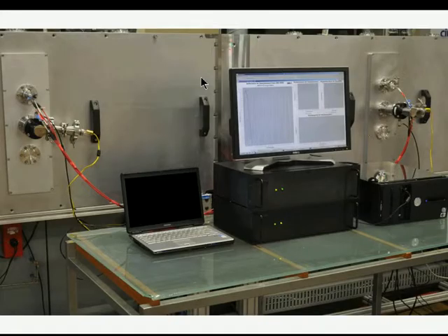On this picture, we are showing how our prototype system was installed in a real manufacturing line. We have installed 2 optical monitoring arrays, one in the chamber where the P layer is deposited and one where the I layer is deposited. The optical monitoring system is installed using this fiber optic vacuum sealed feed-through. There are 2 fiber optic sensors installed inside each of the chambers. They are not visible. One is located on the bottom of the chamber and the other one on the upper side of the chamber, and they monitor 2 different areas of the panel, a bottom area and an upper area.